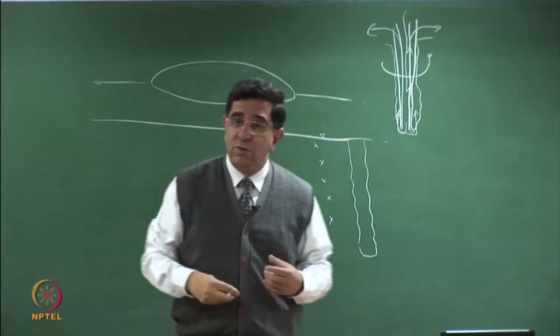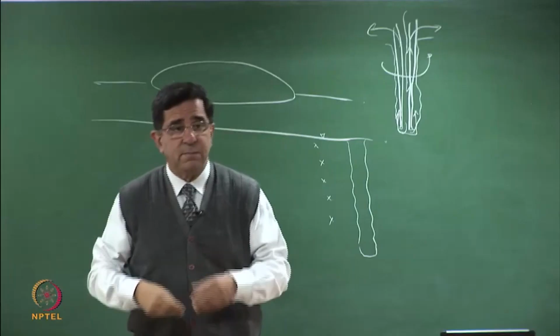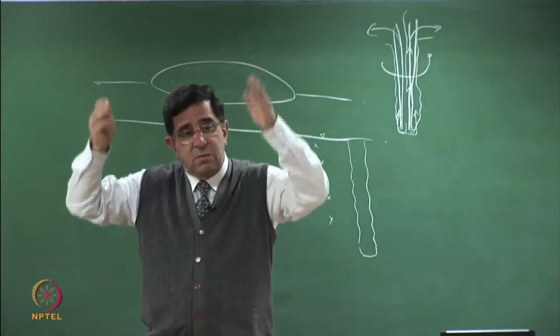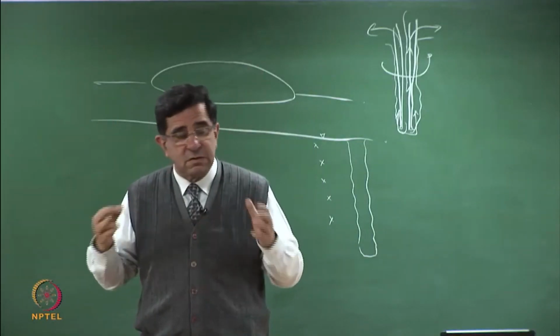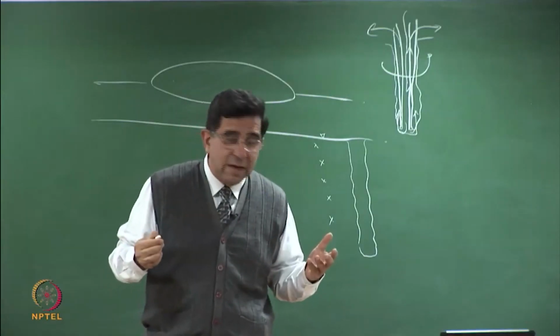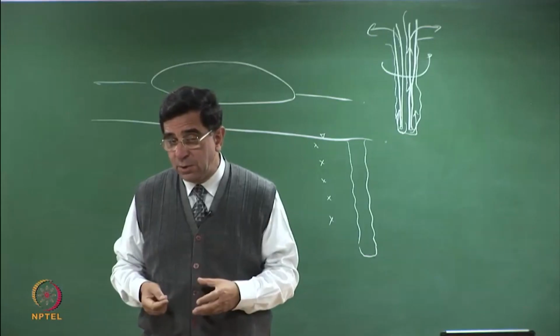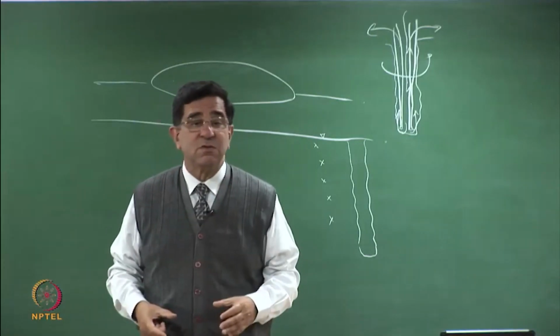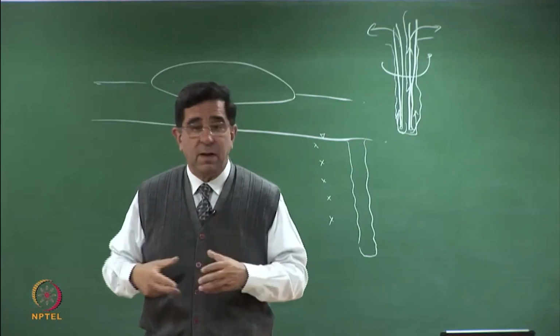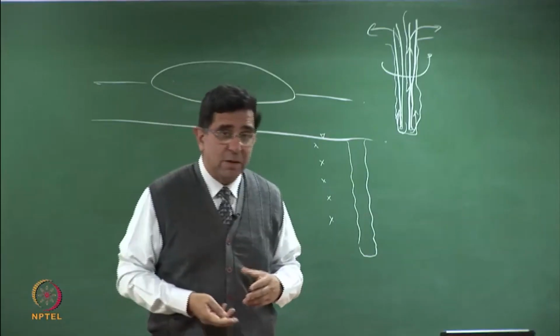It keeps on cutting, you don't take out the casing, suppose you have to go very deep. The slurry which is coming from the annular space between the casing and the borehole carries out the material which has been cut. Once you have reached a particular level, then you put in your pipe with the screens and remove your casing. And in the annular space, you fill up the gravel.